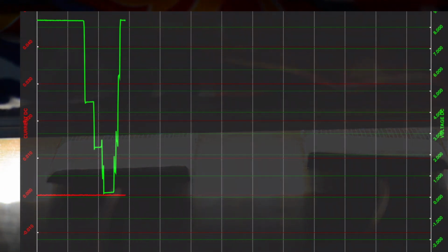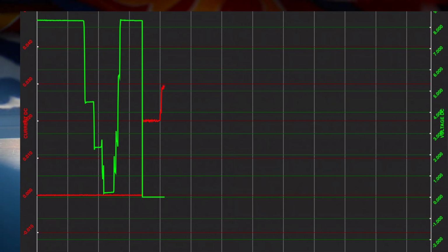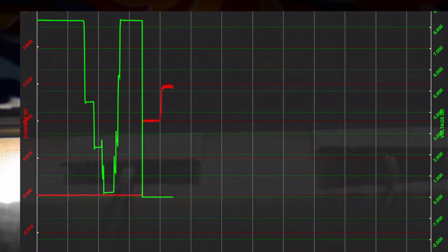So now let's look at the sensitivity of current to light. The easiest way to do this is just to short the generator that you're working with, and do exactly the same thing that we just did. So I'm going to short it. Okay, now obviously the voltage crashed to zero, or very close to, and we're seeing a short circuit current of about 20 milliamps. And if I tune it, I can probably get it a little bit higher. There, it's about 30 milliamps now.